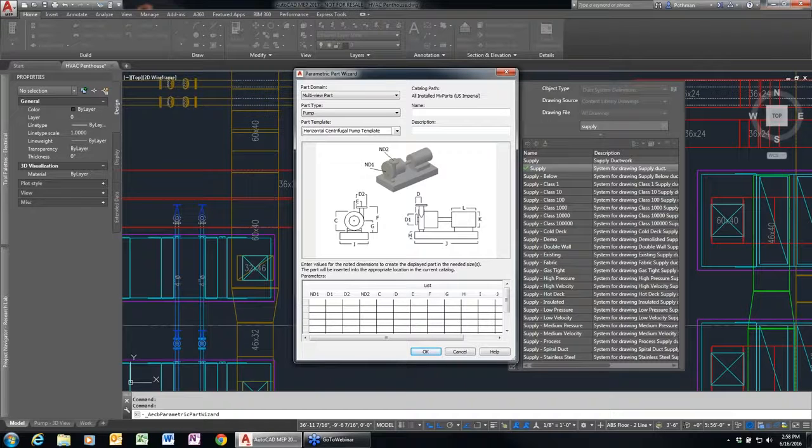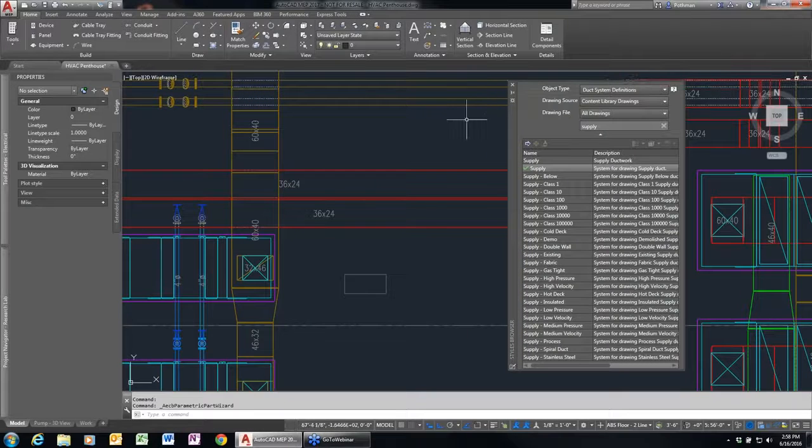I guess one last question here, since we're coming up on the top of the hour. Want to know if things can be transferred to Revit using IFC, and yes, there's an IFC export and import, so you can. It basically will bring the geometry across, but not all the intelligence. You'll lose the intelligence from that, but you can bring the model across.